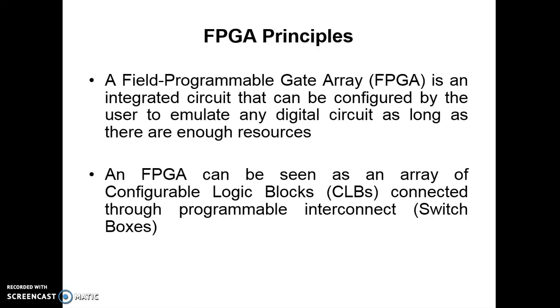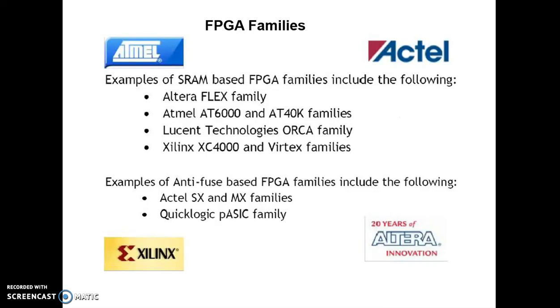FPGA principles. A field programmable gate array is an integrated circuit that can be configured by the user to emulate any digital circuit as long as there are enough resources. An FPGA can be seen as an array of configurable logic blocks connected through programmable interconnects. These are the FPGA families: Atmel, Actel, Xilinx, Altera.